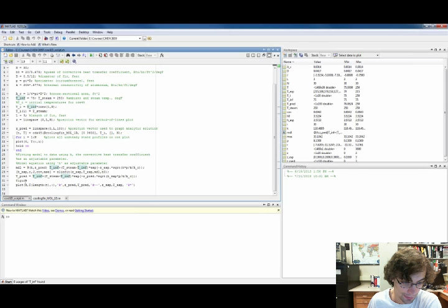This is residuals. Basically, if you take your model temperature, your predicted temperature, what's my predicted temperature minus my experimental, my data point temperature for all the different points. So you can get residuals out, you can get Jacobians, you can get covariances, all different types of stuff. So that gives me my experimental, quote-unquote, h that best fit the line.